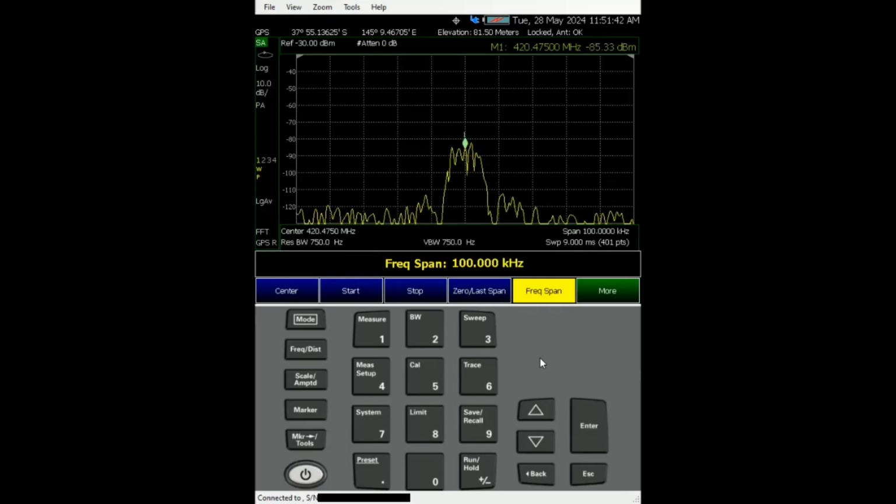Welcome back to my channel, and this is where I'm going to show you step by step how to find the signal and how to do the channel measurements. I'm going to walk around the office building just to show you what type of result we can get from the channel scanner. Mainly, FieldFox is measuring the physical layer information such as the frequency and also the amplitude of that particular signal. So I'm going to reset the hold mode.